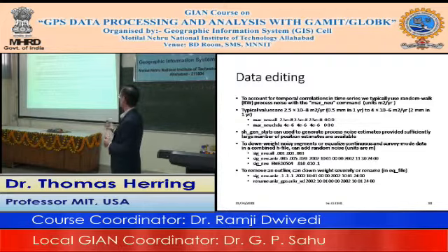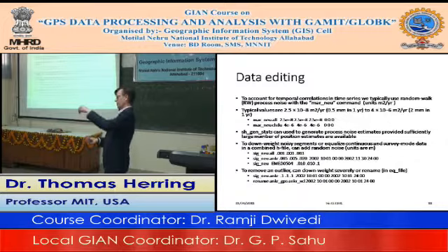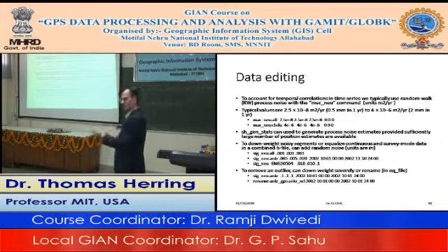So if you have a noisy station and you want to keep it in your solution, but make sure it doesn't influence anything, you can give it a sigma northeast up to increase its uncertainty on a given day. It doesn't change its value, it just increases its uncertainty.